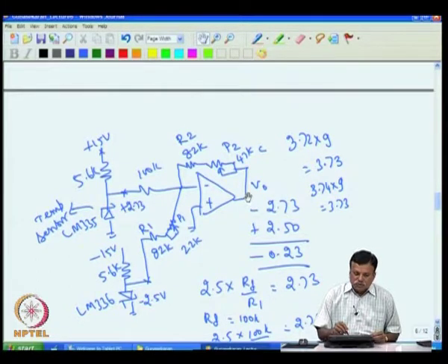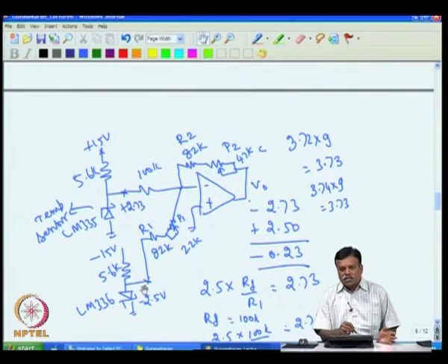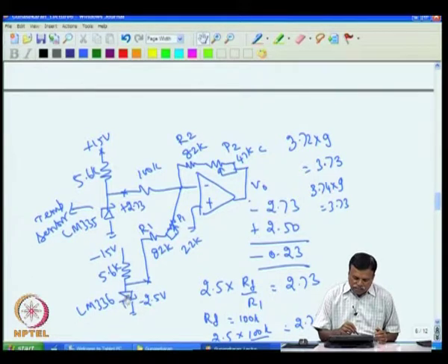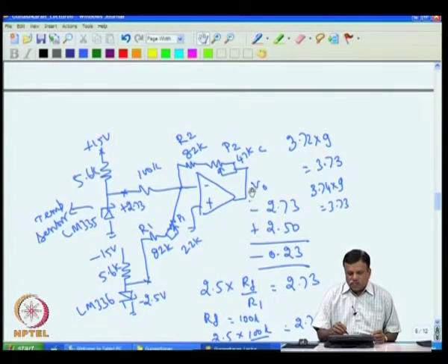That means when the ambient temperature changes, because ambient temperature can change, as I said, for industrial grade equipment from minus 20 degree to plus 80 degree, taking that as a 100 degree change, you can expect a 7.5 millivolt change here, but at this point 10 millivolt is considered as 1 degree C. That means because of the ambient temperature change, the zener voltage changes and the output voltage changes because of that, and you will have an error of 0.75 degree, because 10 millivolt is 1 degree C, and 7.5 millivolt ends up in a 0.75 degree error.